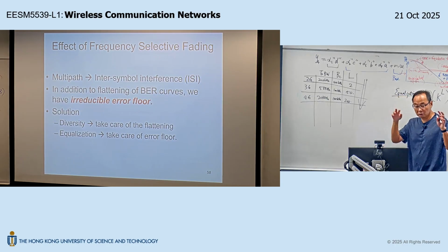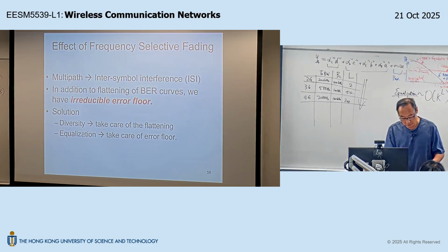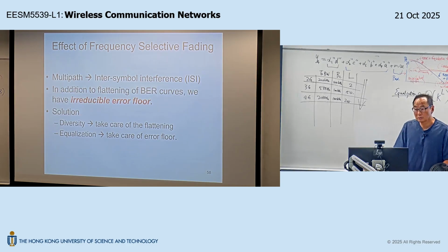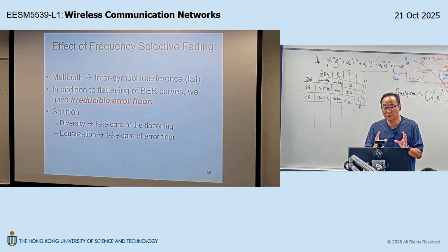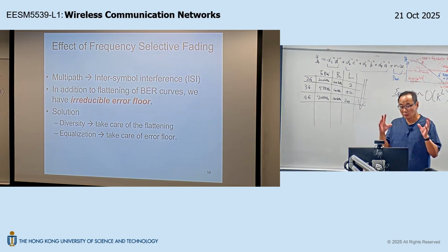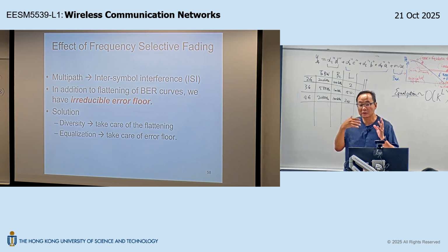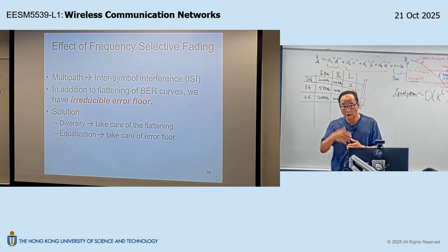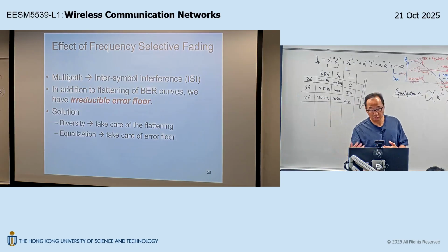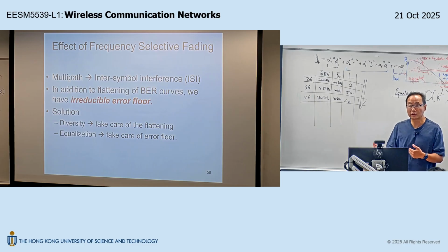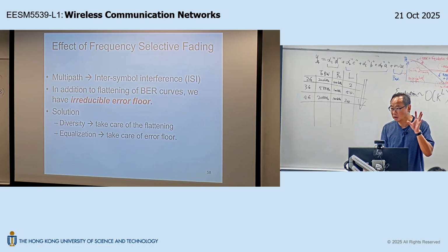So here is a typical solution roadmap. Dumping all the burden to the receiver is not a solution because of that constraint. So in order for you to have some opportunity of low complexity equalization, the transmitter will share an important duty. The transmitter can send some signal with some built-in structure, and the receiver, by exploiting this built-in structure, may have the possibility of low complexity equalization. I repeat, the transmitter shares an important duty of sending out signal with some built-in structure.